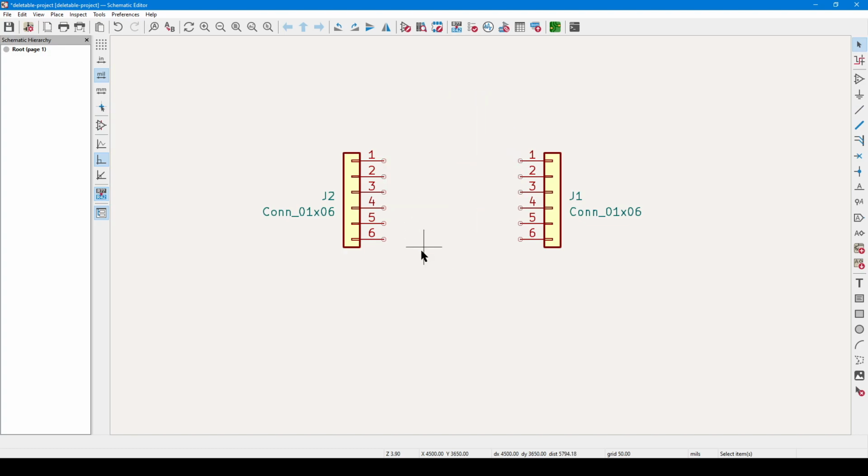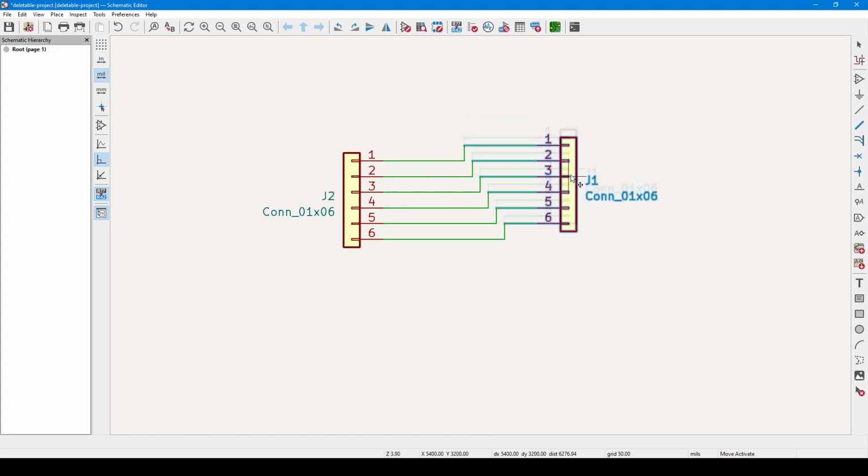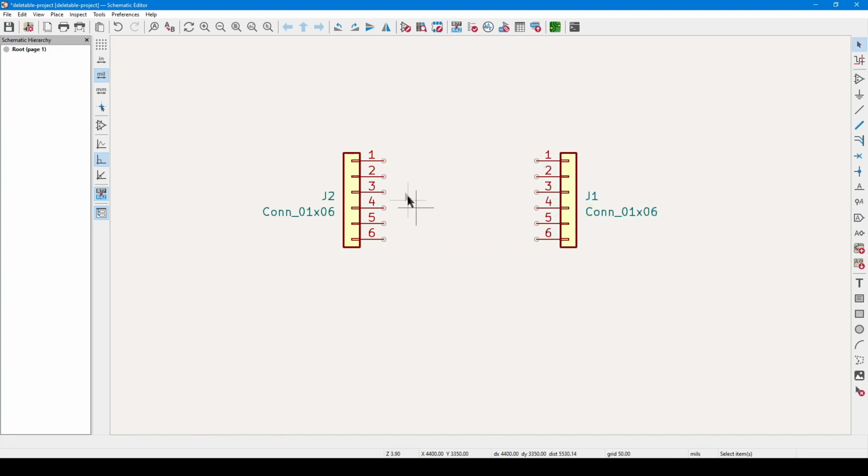The third method is a bit unconventional. Between these two connectors on the screen, I'm going to position them such that their unconnected pins are overlapping, and after I set it down, I can click and drag them apart, and then the wires are going to automatically appear. And really, now that I said it out loud, there is a fourth way to do this.